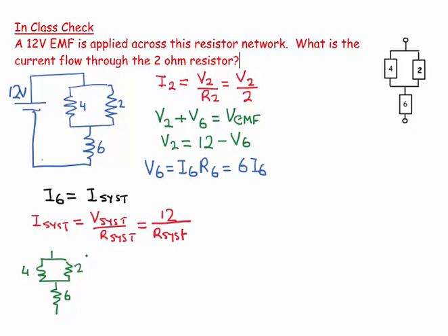So the first thing to recognize is, let's do this parallel bit. This parallel bit is kind of unambiguously in series with the 6 ohms. But if we try to do the series bits first, would you take the 6 with the 4 or would you take the 6 with the 2? So that's not the way to go. Do the unambiguous bit first.